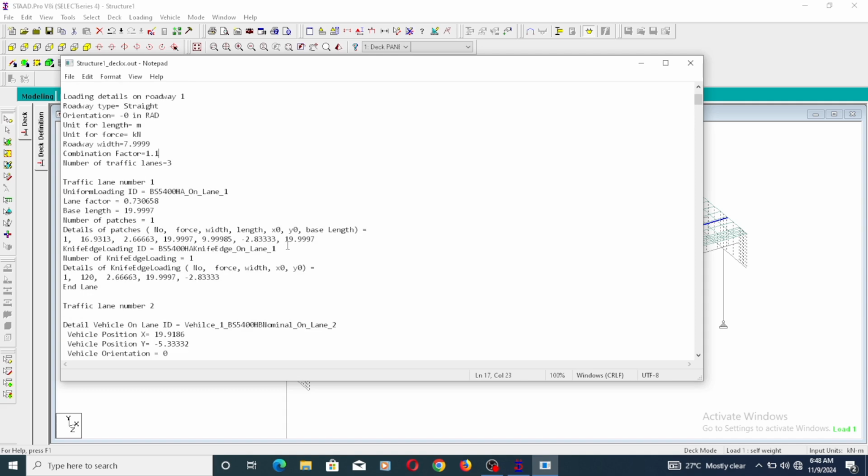All right. So let's just take a look at the various loads. We can see that the influence surfaces are generated for each of these loadings, which the system has used to calculate the load position for maximum effect. Okay. All right. So having looked at this load, we are going to go straight to exporting it into the Staadpro model. All right.